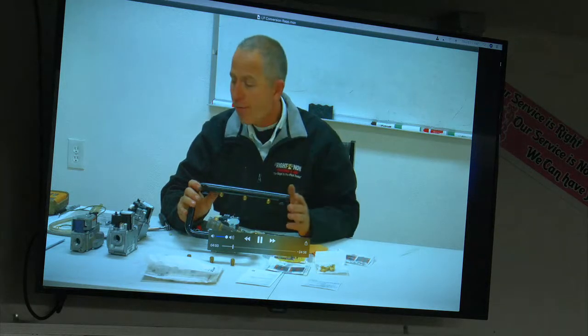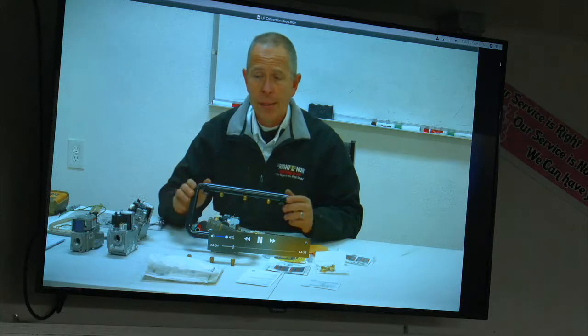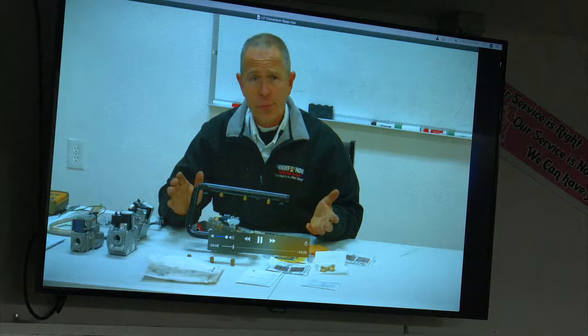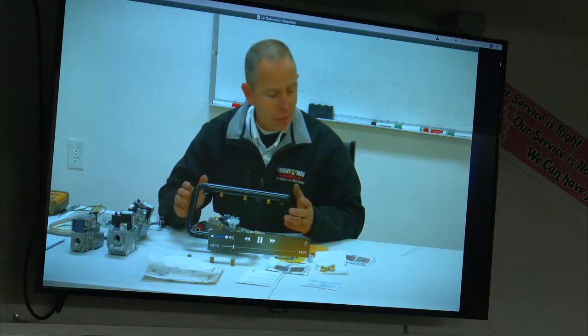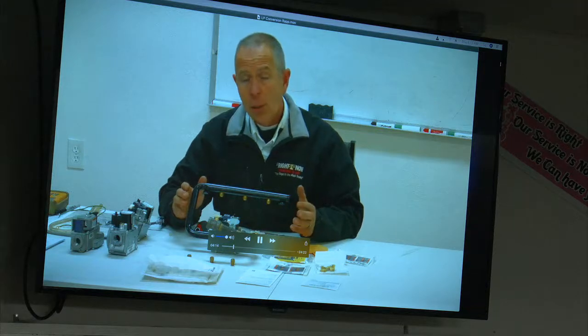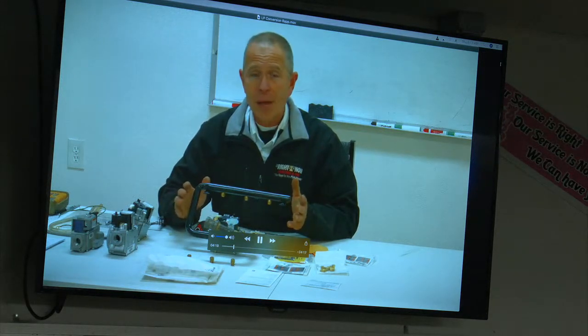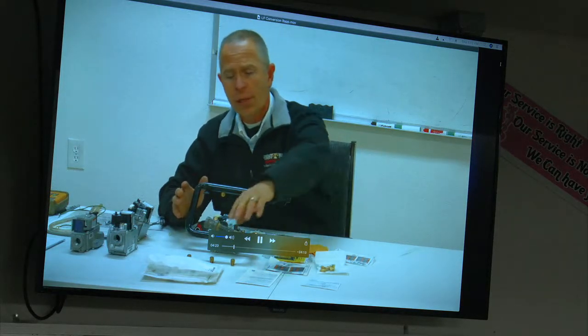So when we do that, the first thing we're going to do is match up our kit. And there are various different valves. There's White Rogers, there's Honeywell, there's Emerson, there's Gemini, which will be used with either Goodman or Rheem; they will have one of those styles of valves. They will send you the kit. With the Rheem furnace, right on the outside of the cardboard box, it will actually tell you which kit you need to use to convert it.